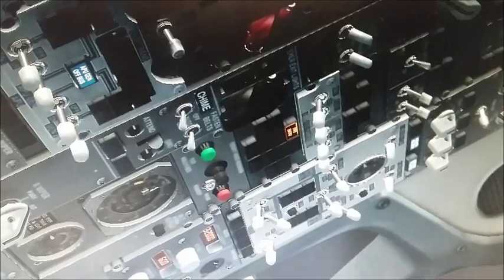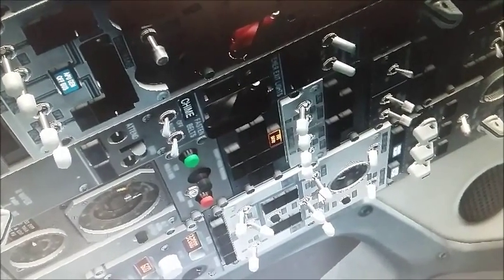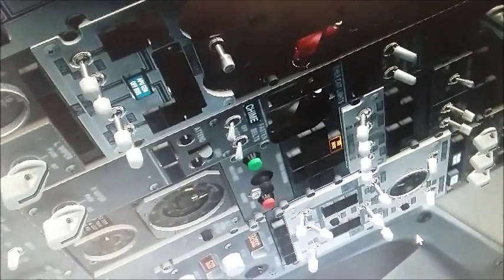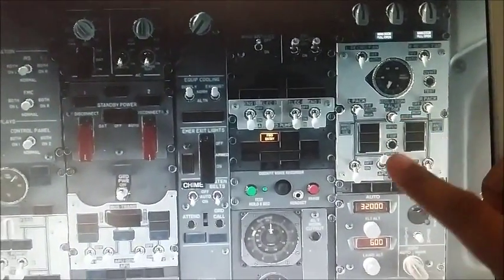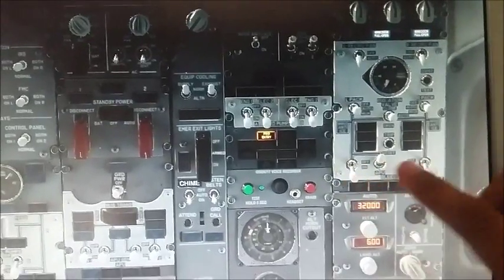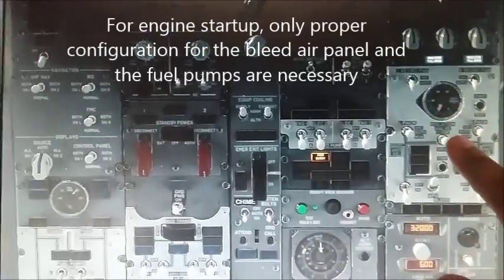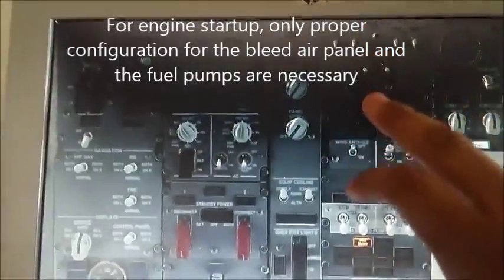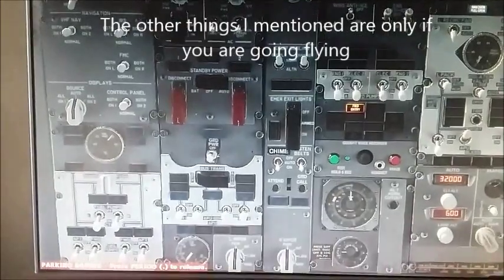And then for the bleed air panel, you can close the APU bleed valve and turn on the packs. You can leave them in auto, or you can put them in on or high, whichever your 737 has. And that's it. And this is just a better view of the bleed air panel. Packs in auto, isolation valve in auto, APU bleed valve off, and the engine bleed valves on, because we want the air from the engines to give air to the rest of the aircraft. Also, I forgot to mention, make sure the hydraulics are in, and the window heats and pitot heats are on, and the fuel pumps.